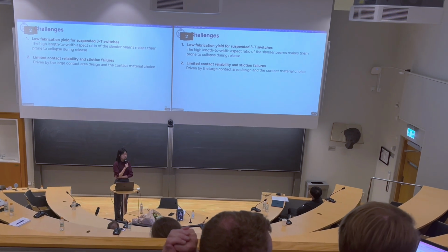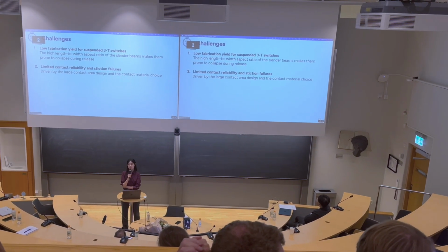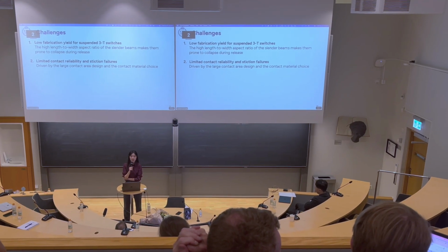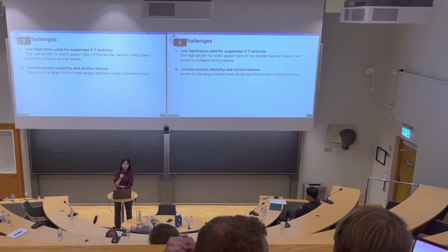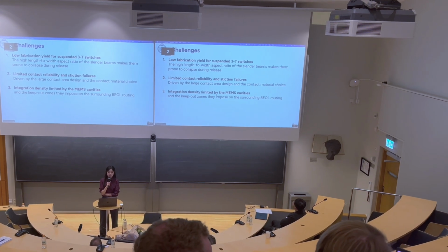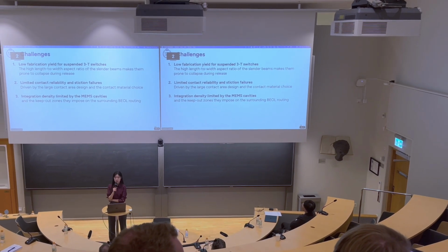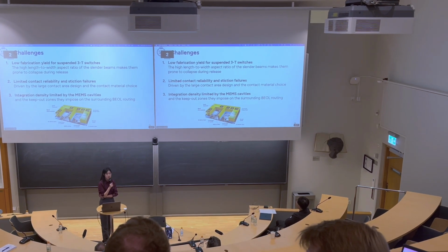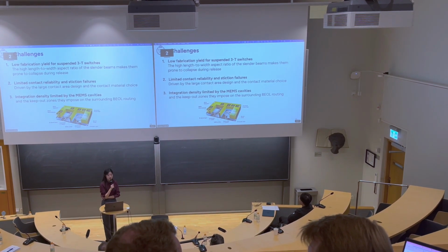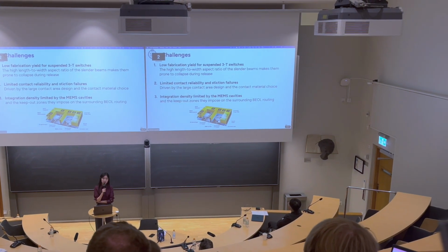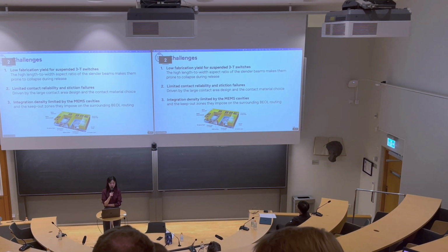And second is the limited contact reliability and stiction failures induced by the switch contact design and also the contact material choice. And third is that this integration approach has a limited integration density, because here you can see the switch is sitting inside the lens cavity with the back-end routing surrounding it. So it's a 2D planar integration method.